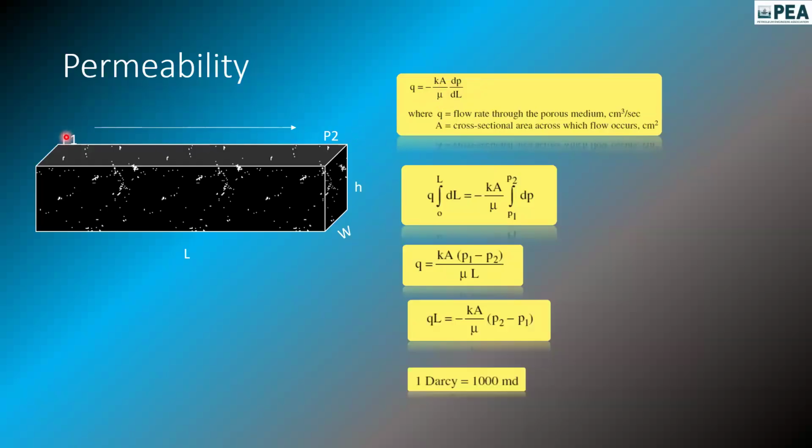Because fluid will flow from high pressure to low pressure, so there should always be some pressure difference. Like the pressure we discussed earlier when talking about the radius of investigation, high pressure is at the boundary and low pressure will be near your wellbore. With that pressure difference, flow will happen. And dL is the change of length, from where exactly it started to where it has reached. And mu is viscosity. So this is the equation.